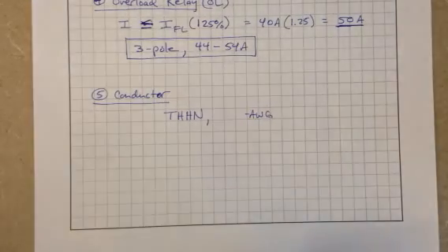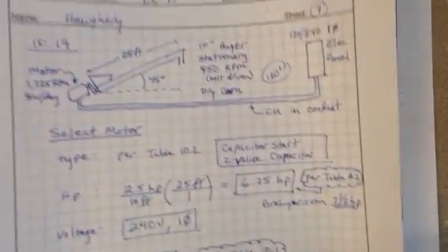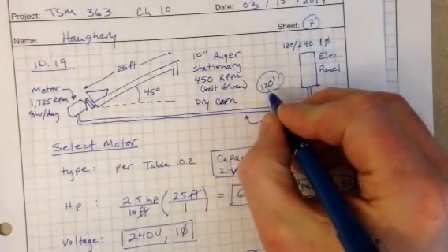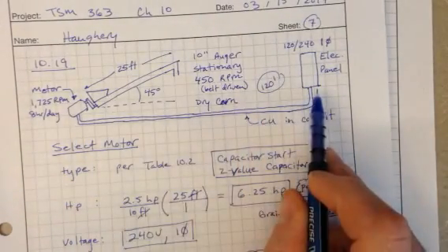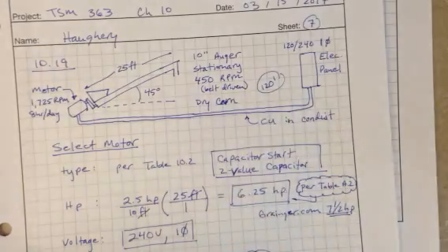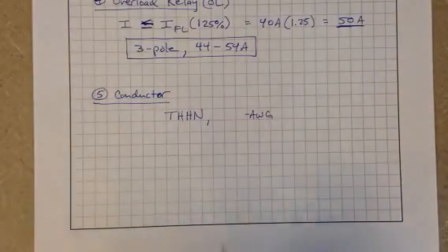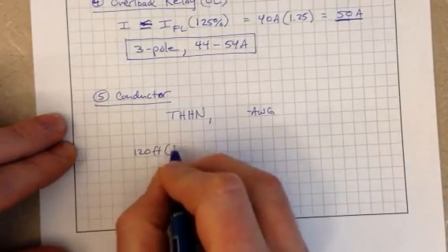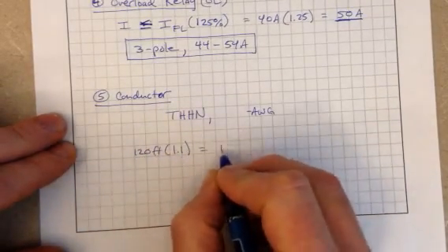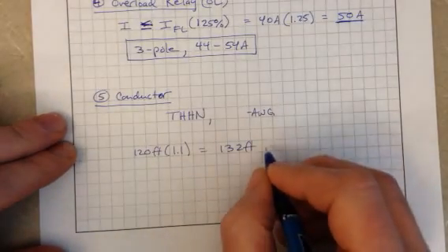So we can look at two different things, ampacity and voltage drop. One thing I failed to mention previously, we have a 120 foot dimension between our motor and our electrical panel. Okay, so 120 is our single one-way distance. Adding 10% for connection, so we have 120 feet times our 10%, 132 feet one way.